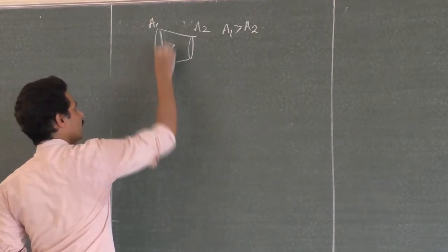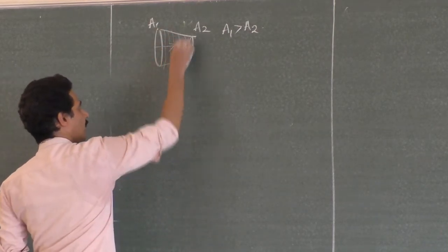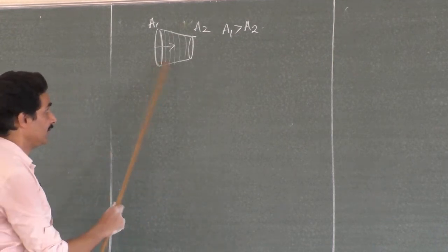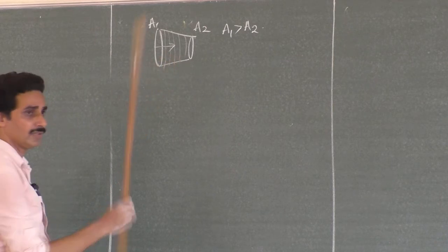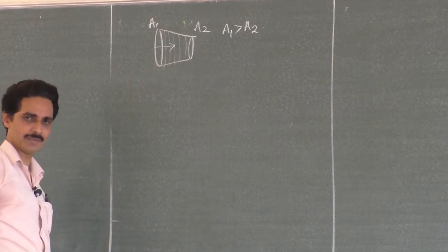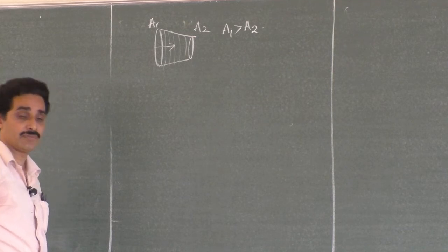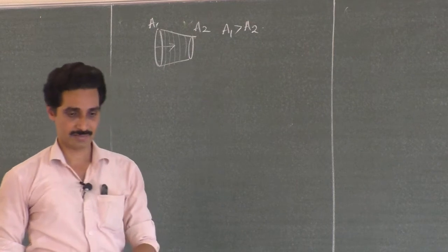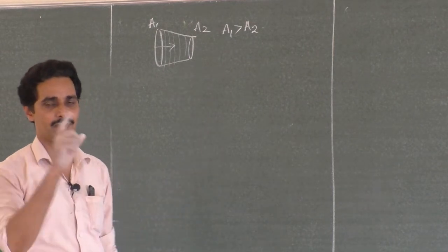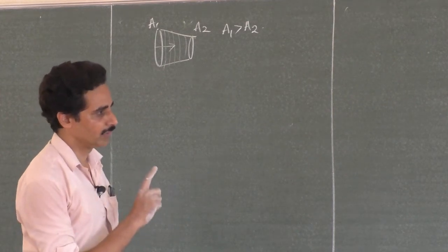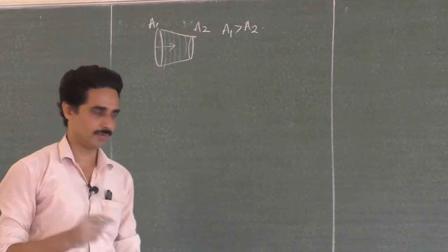You divide this into different parts like this. Will you get small coin-like arrangements? And will they have different resistances here, right? The resistance of each will be different, because their areas of cross-section keep on changing. Now, is it not like different resistors in series? Whatever be the amount of resistance, when you connect them in series, definitely what is same? Definitely, current is same.